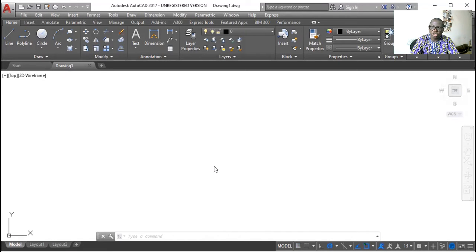We have snap to locations on objects. We call it object snaps. Instead of entering coordinates, we can specify points relative to existing objects, such as the endpoint of lines, center point, or midpoint. So all this can be used to snap. These are precision tools that we can use in AutoCAD. Snapping to locations on objects, we call that object snaps.